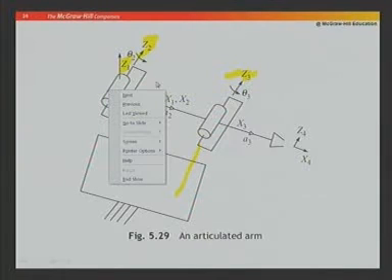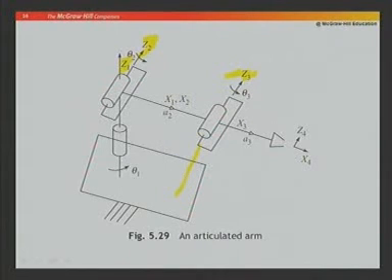So, now I have put the common perpendicular to Z1 and Z2, x2, here. Then the common perpendicular to Z2 and Z3 is x3 here. Okay. So, I have set it up. Now, the two arbitrary ones are the first and the last one. So, one may think to put x1 here, but if you think carefully, putting x1 here and here does not make any difference as far as the motion is concerned.